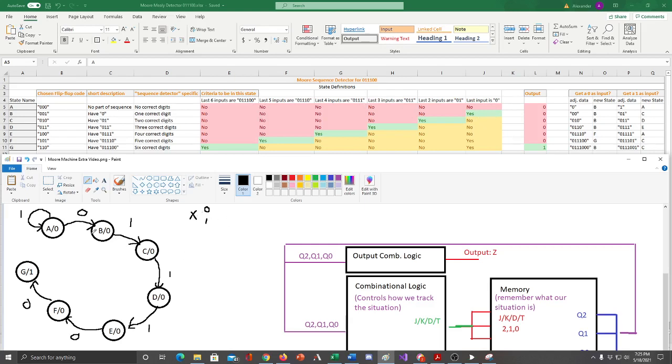So that's fine. Now in state B, in order to get to B, we have to have obtained a 0 most recently. So you can see over here in this table, I forgot to point it out. In state A, on a 0, the data becomes a 0, which meets B. And on a 1, it becomes 1, which does not meet any state higher than A. In B, we have a 0 for sure, and our next result could be either a 0 or a 1.